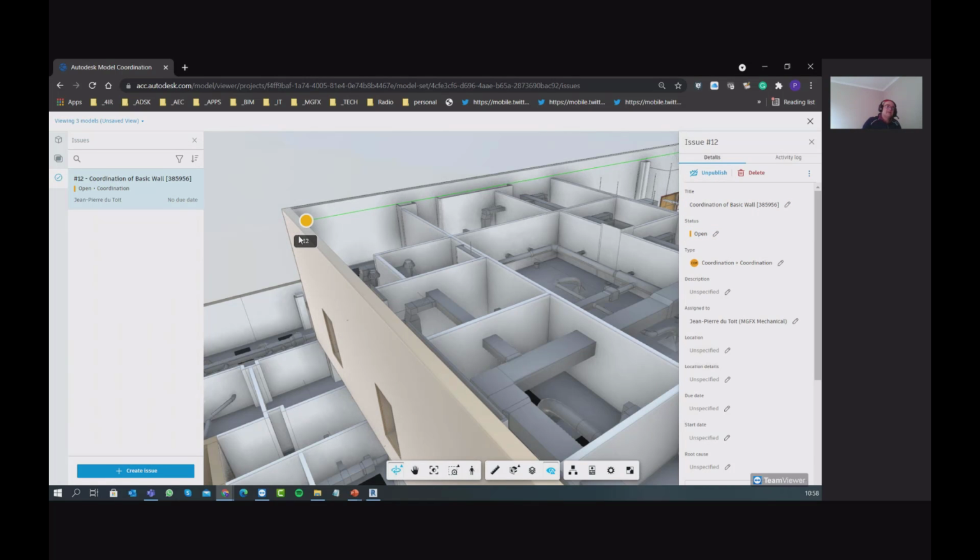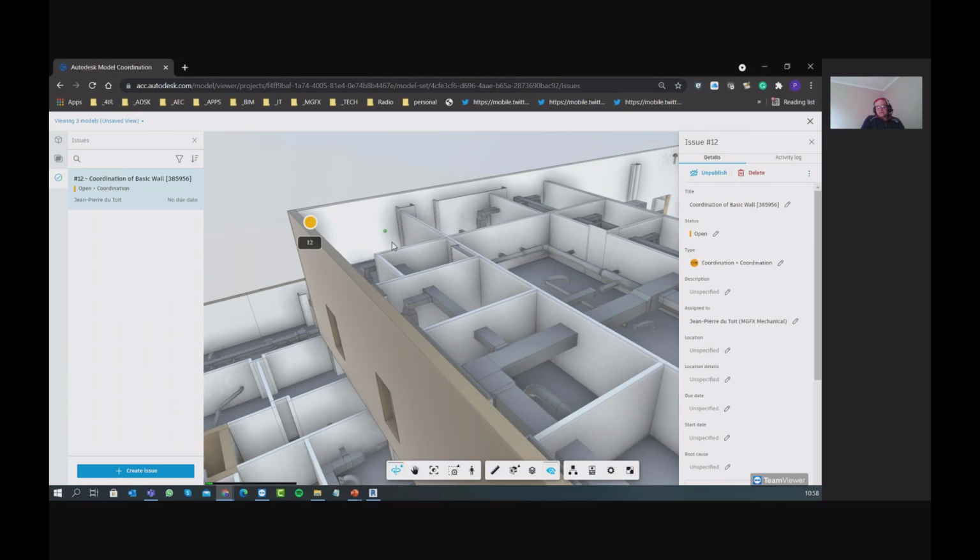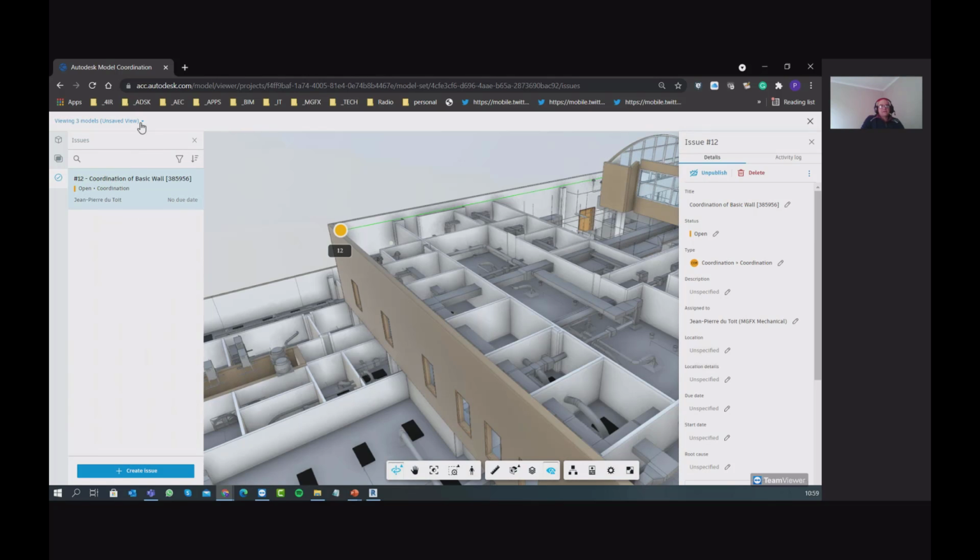So typically what we would like to do is to isolate all the clashes that are relevant just to our team for this week, so that we can sort it out internally based on what the other guys shared last week. And then next week, the second week, we do a proper clash detection to say, right, how's our model going to interact with another discipline's model? And then we will take that up with their managers and say, right, look, our models are clashing over here. I know you're the structural guy, so you can't move your column. I'm the mechanical guy, so I'm going to have to move my duct around the column, or the piping, or whatever is required.